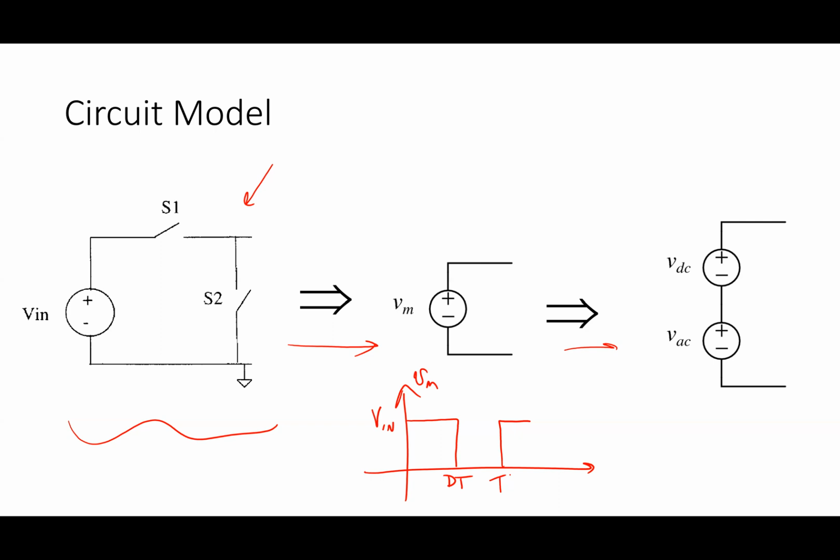So we can go into the math and write all those. We're not going to write the math down on that, but fundamentally, you guys know what that means, right? There is a DC term. This function is represented by a DC term plus a bunch of sinusoids, right? So I can think of that because they're all added together. I can think of this voltage source as being the superposition of a bunch of other voltage sources, right? Basically a DC voltage source plus a bunch of sinusoidal voltage sources, right? So what I've done here is I've said VDC and all the harmonics can be separated out into two different voltage sources.